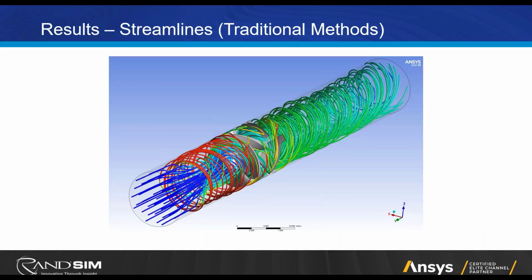Next slide, please. Okay. So, this streamline plot is typically used to get an idea of what the flow is doing in 3D, and generally it's very insightful. But you can see in this case, it just looks kind of like a mess. A lot of spinning, swirling. You can't really tell what's happening. But one thing that is interesting is the amount of pre-swirl that's evident here. You see the red upstream of the impeller. Yes, so we're actually inducing swirl in the flow prior to the flow getting into the device. And that's going to be important when we talk about blood damage shortly.